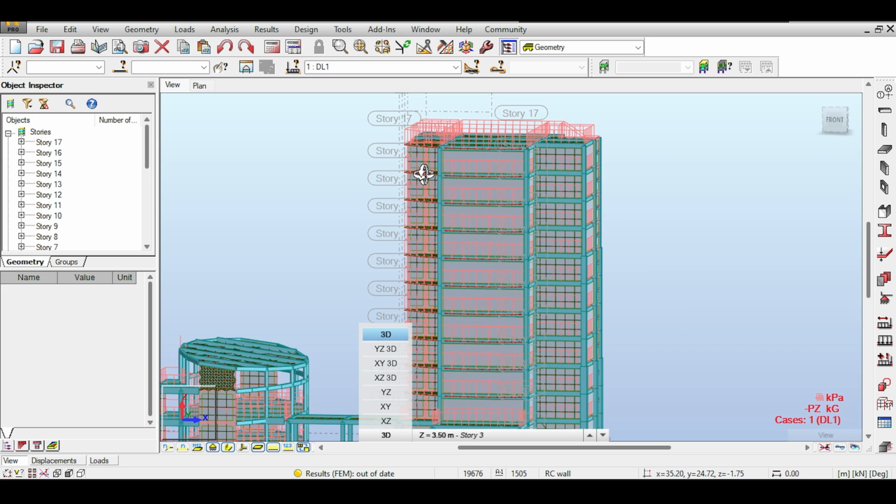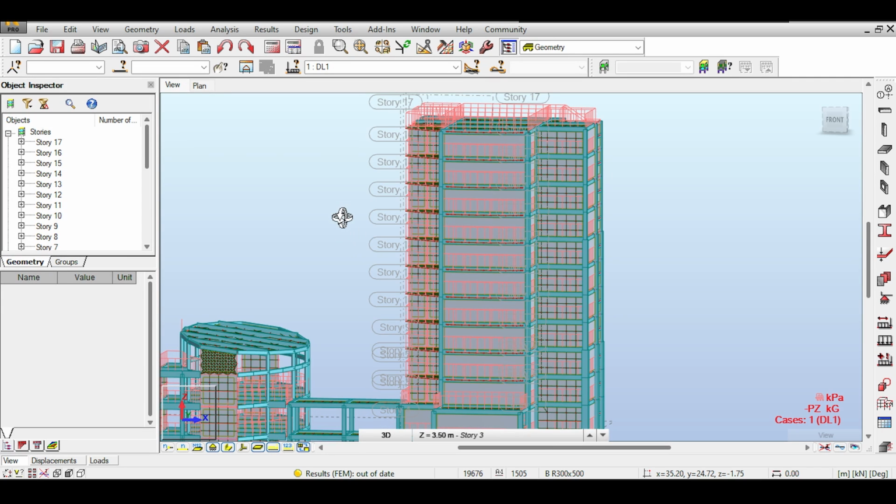Then usually my sections are bigger than what I need. So then starts a trial and error cycle. You see, what I do is I have a section, I run the design, I get a ridiculously low steel ratio, so I know that my section is over-designed. So what I do is I make my section smaller, and then I design again. I keep making it smaller and redesigning, until I start seeing that the steel is increasing a tad bit above the minimum.